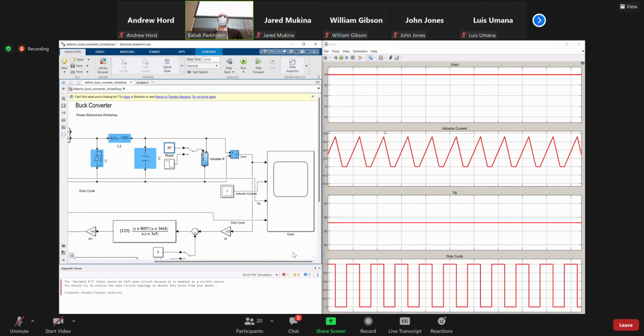The impact of DCM is when you have an active device with substantial losses, let's say during recovery. If you have DCM, there are no recovery losses showing up. And it's more complex. Later on, we'll see that the control is a little bit more robust. But definitely the characteristic is different. It's a bug, but it's different.